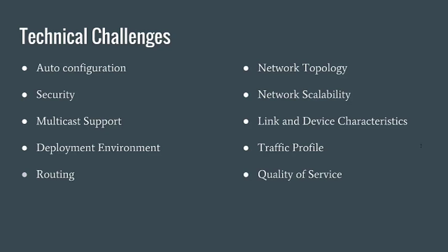Also, the network should be scalable. The typical network would have hundreds of sensors for measuring and routing purposes. The SHM network does not have any particular quality of service requirement other than low latency and reliable data delivery. The network should provide support to verify the data source. Even though the sensor data is public information, the data collected should be from trusted sources. Typical SHM networks are deployed from extreme outdoor places to less demanding indoor locations. And the SHM network should also be fault tolerant without human intervention except for device failure.